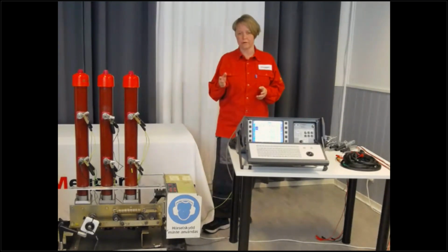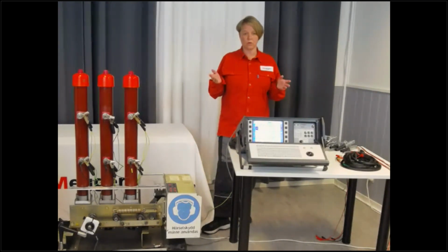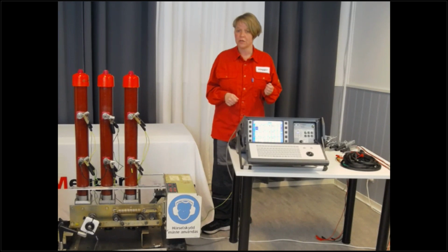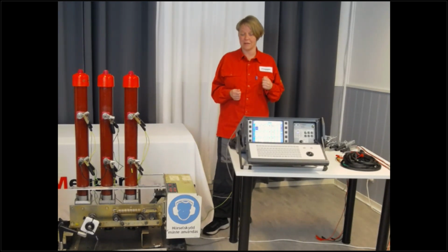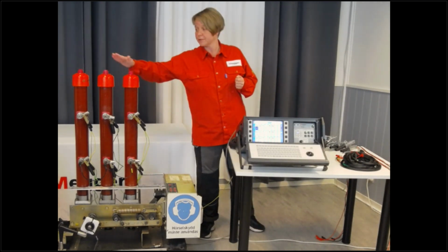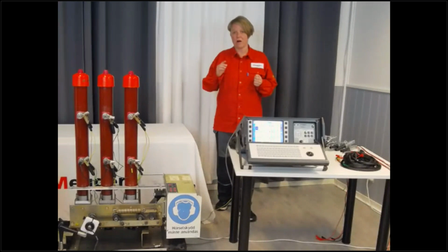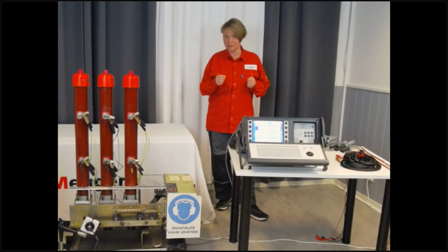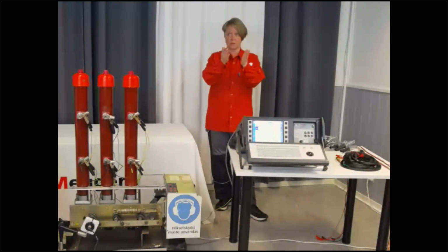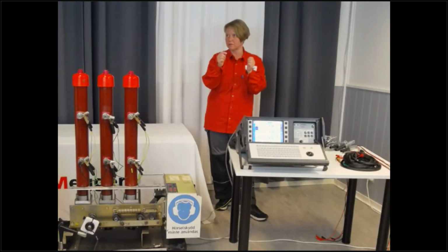on an outdoor breaker, it is important that you use grounding equipment which is separate per phase. There are types of grounding devices which have three parts, one for each phase.